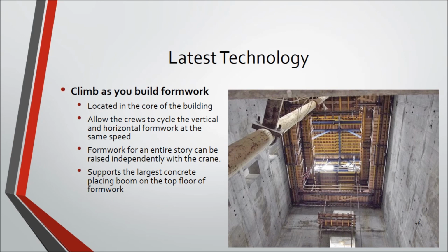Second one is climb as you build formwork. This is a self-raising hydraulic formwork located in the core of the building. This allows the crew to work in the vertical and horizontal formwork at the same speed. It can support the largest concrete placing boom on the top floor of formwork. Its specialty is that the formwork for an entire story can be raised independently with the crane.